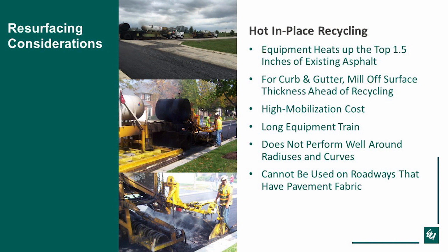So those are all kind of different resurfacing considerations that would go into your traditional resurfacing options. An alternative would be to do hot-in-place recycling. So what the hot-in-place recycling is it's a train of equipment that goes through and heats the asphalt back up to 300-400 degrees into a working condition. It takes a scarifying unit that goes through and scarifies off about 1.25 inches to 1.5 inches deep. It'll go back through a screed, and then it'll get paved back down, and then you would put a new layer on top of that.